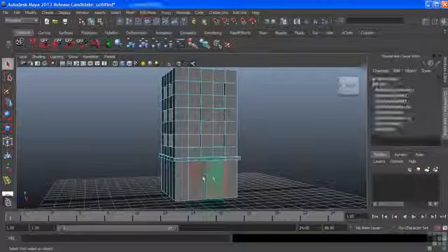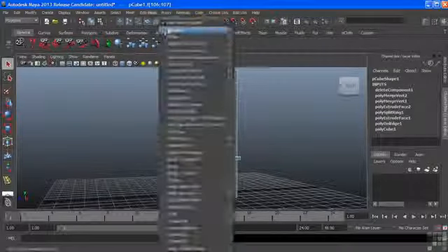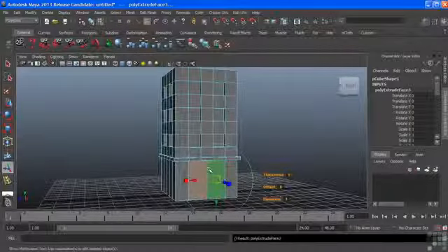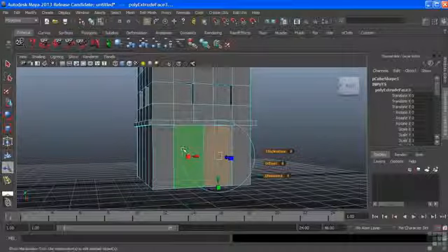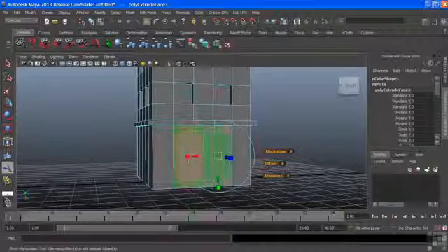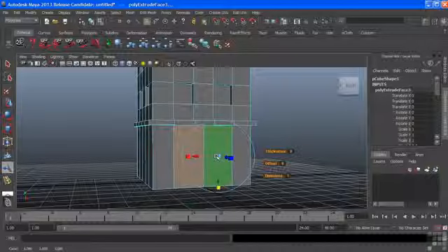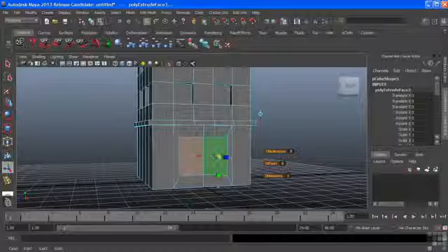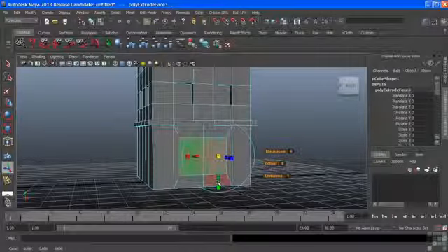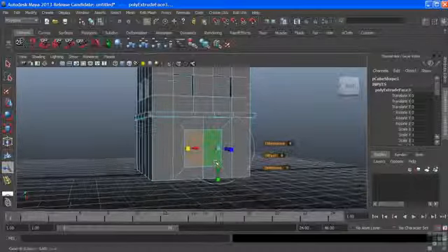And we'll go back to faces, and I'll add another extrusion here to start bringing out a door. And this time I'm going to scale this down. We won't use the actual size of all of those faces. So I'm just going to click any one of the scale icons there, which are the cubes, and that's going to bring up the middle scale manipulator. And we'll just scale this in. We get roughly the shape that we're looking for, a large front door. That looks pretty good.